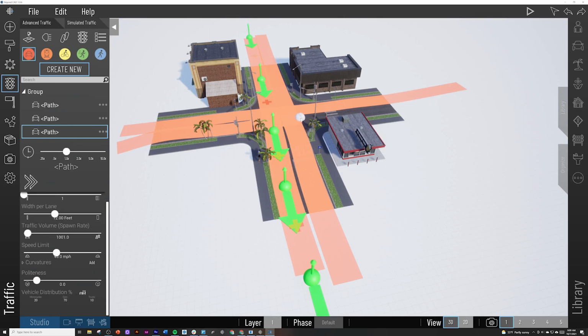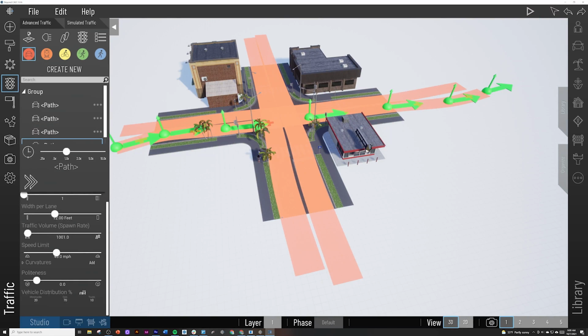And if you've used visualization engines before, you may have noticed that a lot of times there's not much you can do as far as the intersections without vehicles going through each other. But we're gonna work on that. You might notice my numbers. I'm not doing exactly 30 miles an hour, exactly 200 vehicles per hour. The reason I'm doing that is because it just makes it a little bit more organic if everything's not exactly the same. And that's often with the visualization what you're trying to do.